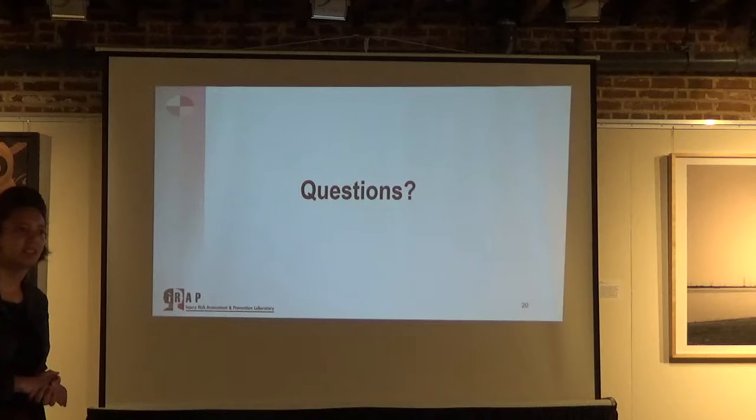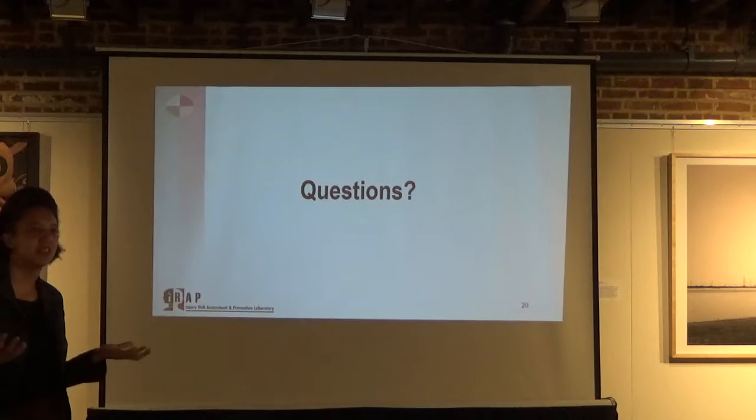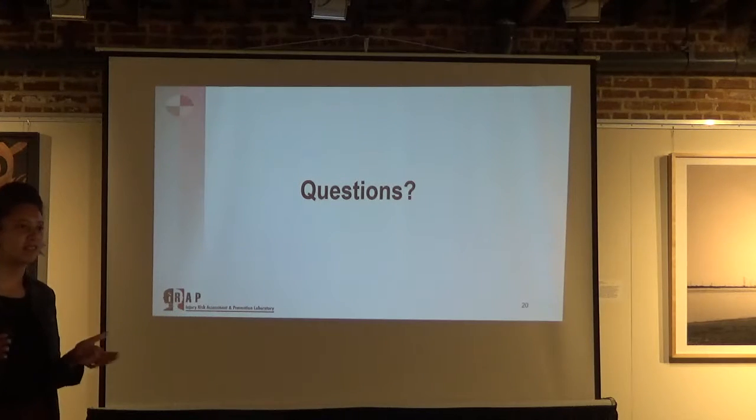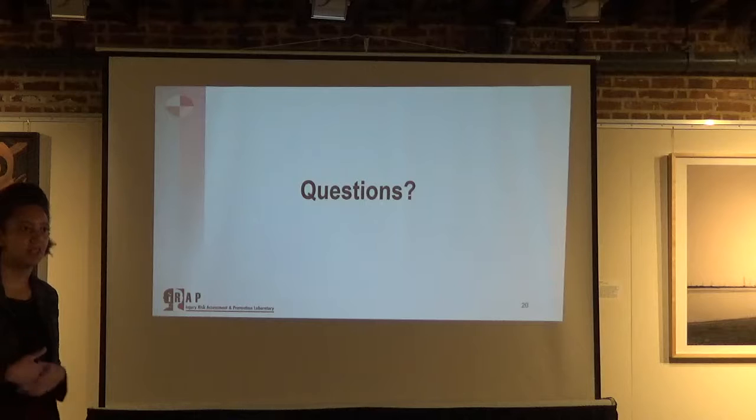I just looked at the peak stresses, just because we don't know how much of the adult data modeling applies to pediatrics. Using a more linear model for now seems the safest approach. And the studies that have used linear elastic models have found it does correlate pretty well with fracture when you use the tensile yield strain threshold. So for an initial evaluation, we felt that this was appropriate.